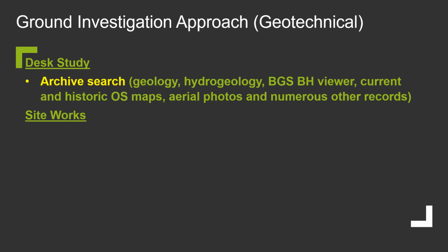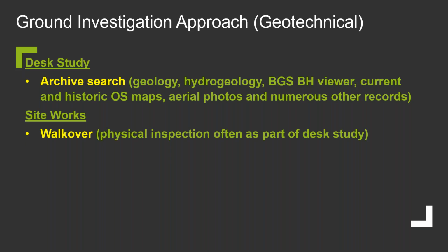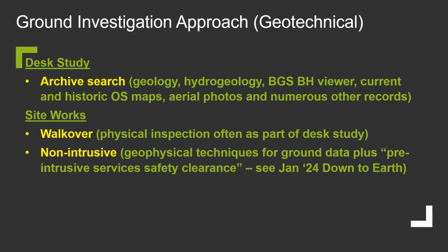The desk study would primarily be your archive searching. We're pretty lucky really in that the geological maps and previous history and experience amongst consultancies will tell us what we're expecting. Aerial photographs, ordnance survey maps, historical information, lots of archived information will give us greater confidence. The site works themselves, you might argue that the walkover could take place as part of the desk study. But if it didn't, then certainly before the site works start, you're definitely going to be doing walkovers to check access, etc. And then the non-intrusive techniques can indeed be utilised.